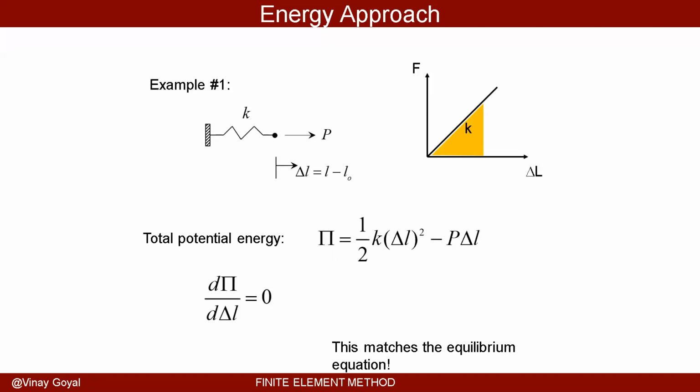And to illustrate, in example number 1, say I have a spring, and the spring has a load applied P here. That load applied P will stretch that spring some amount, delta L. So then in that case, for the total potential energy, and you should know this, the spring energy is 1/2 K delta L squared. That is the energy under this curve, force F relative to delta L. That's the area under this curve. And that can be quickly derived if you're curious where that comes from,